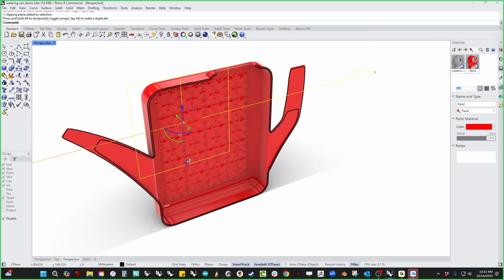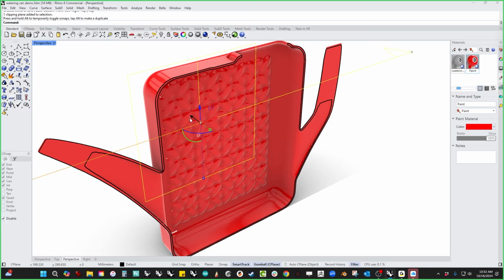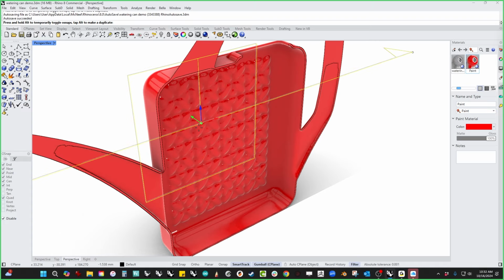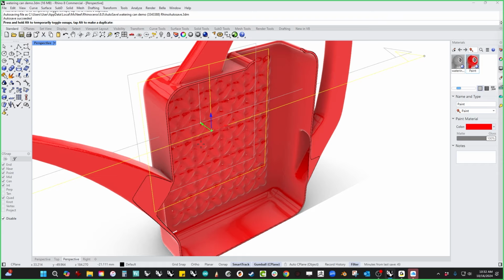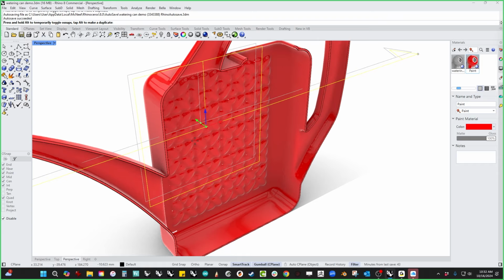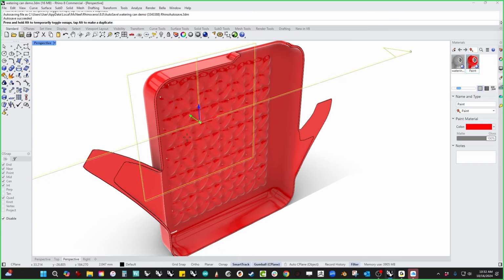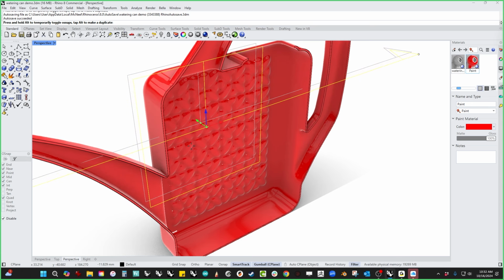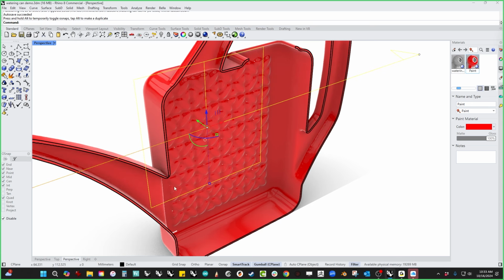And this clipping plane exercise is a good thing to do. So when this printed, that inside corner right there would be a little bit too thin. So I would need to pay attention to that. So I'd probably go back if I was going to do this and remake the plug. I'd either offset it a little bit more, or I'd add smaller target edge length so that it would suck down into this corner a little bit more.